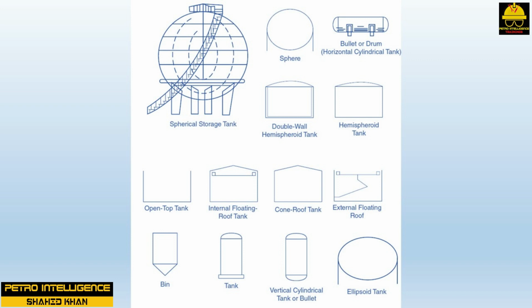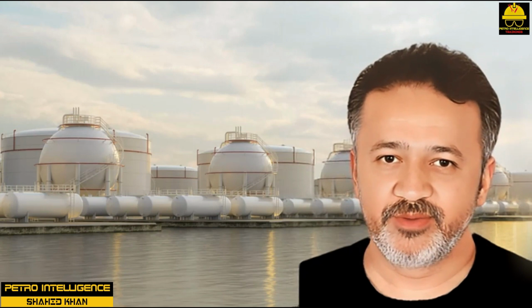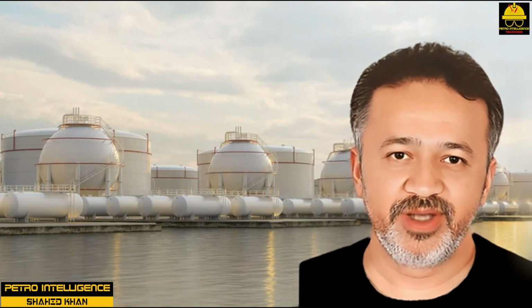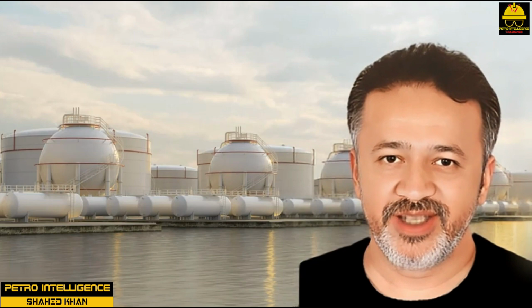Tanks can be divided into 4 general categories: atmospheric tanks, low-pressure tanks, 0 to 2.5 PSIG, medium-pressure tanks, 2.5 to 15 PSIG, and high-pressure tanks, above 15 PSIG. This picture shows the different types of tanks found in the chemical processing industry. Atmospheric tanks can have a cone roof or a floating roof. Process technicians refer to a tank as being atmospheric when it is properly vented or designed to be run at 14.7 psia, pounds per square inch absolute, or zero gauge pressure, that is, 0 psig.